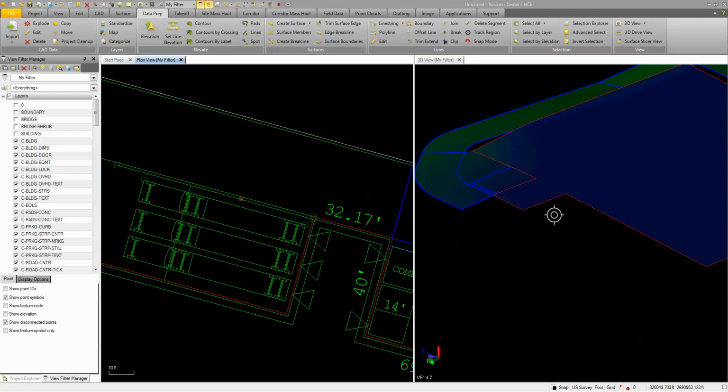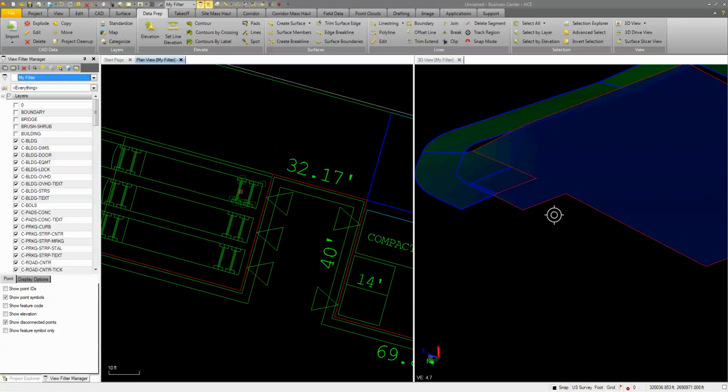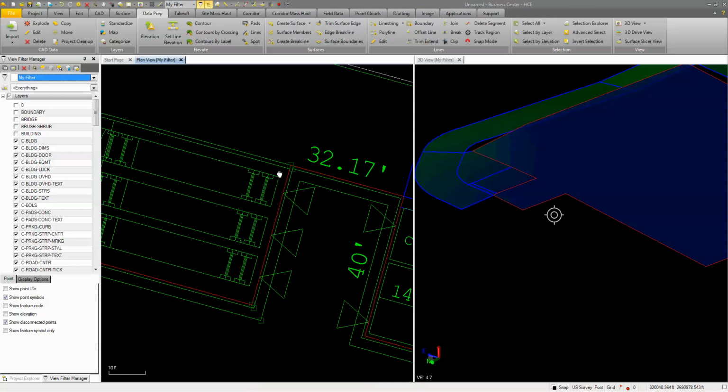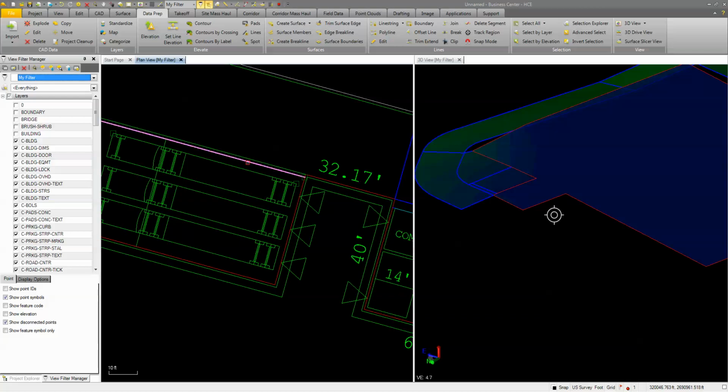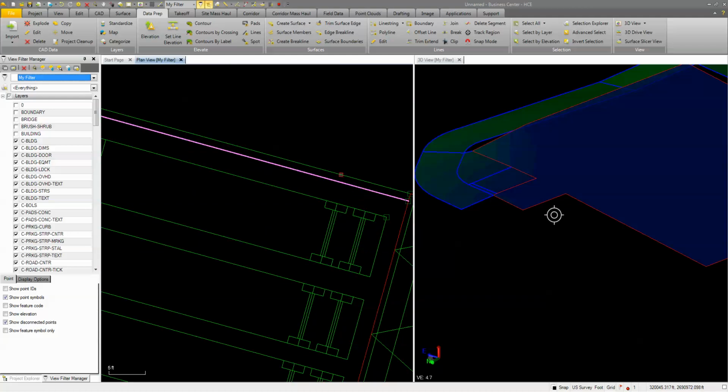Now we're going to turn our attention to the loading dock area. What we're going to do is start at the back corner of the building, which is right here, and use that elevation. We also have a line here that is a retaining wall. It's a 1 foot wide retaining wall, so we're going to have to account for that, as well as this is the flow line for the curb.